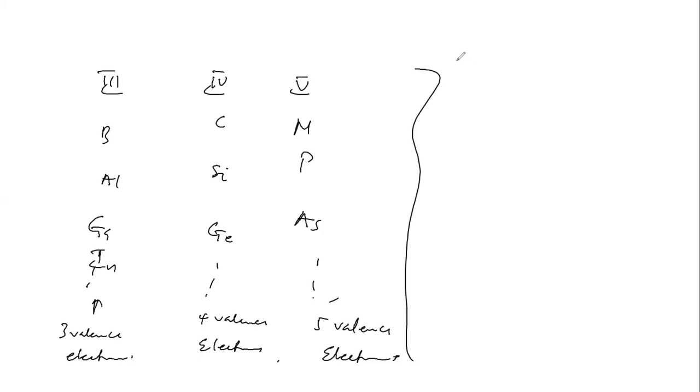Now, coming from the intrinsic perspective, where they exist in their pure form, okay? Once we have some of these atoms, they form some kind of crystal. So let's assume I take silicon, for instance, which has 4 valence electrons. So for the silicon, we're going to have something like this. We have 1, 2, 3, 4 in the outermost shell. So this can also bond with another silicon atom, where we have 1 here. So that forms a complete bond.